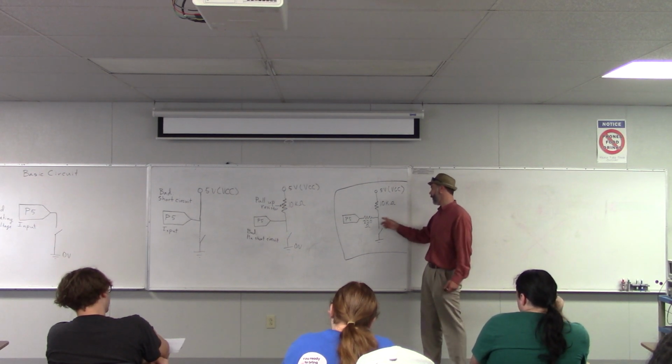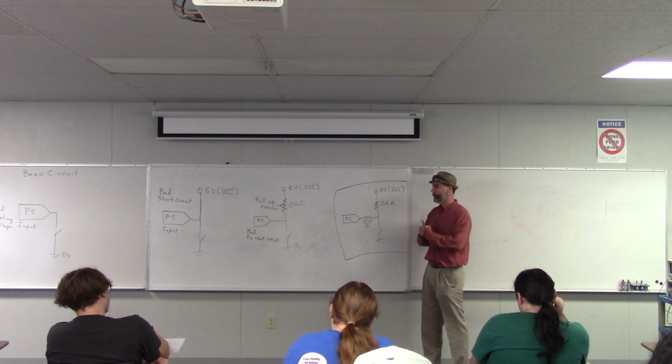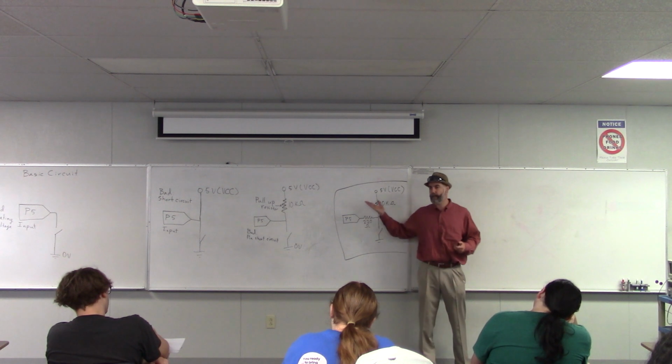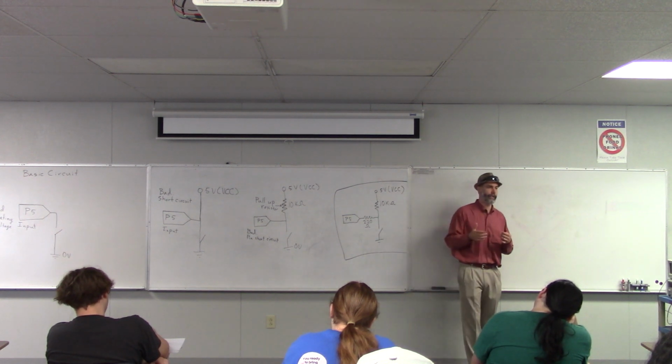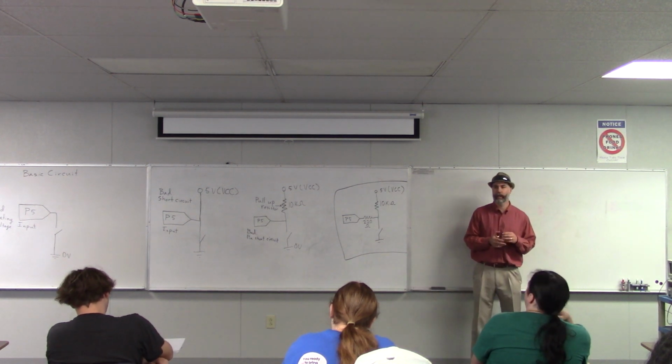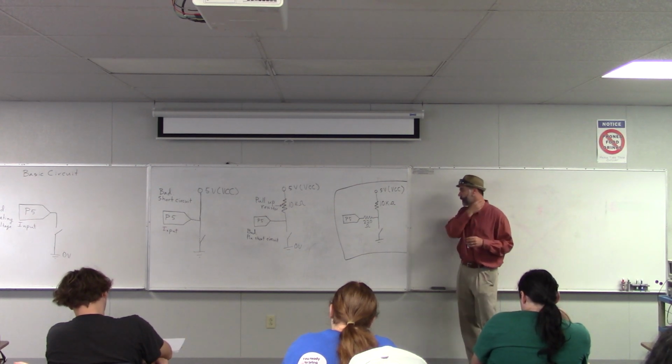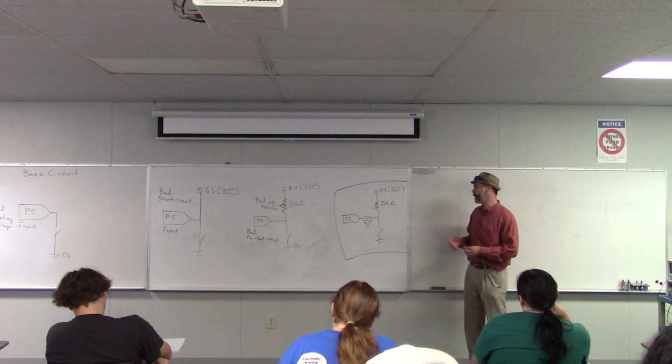So when the switch is open, the voltage is at 5 volts. When the switch closes, the voltage goes to 0 volts. And the pin voltage is never floating. It's always predictable, and predictable is what you want, especially when you're controlling movement and things based on that. Okay? So this is the circuit.